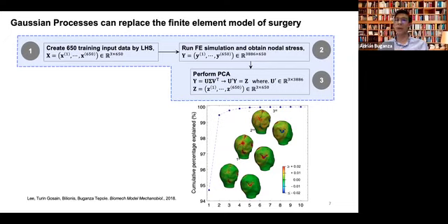So if you, for example, normalize the stress data, if you subtract the mean and divide by the variance, you can do a principal component analysis. And the eigenvalues essentially describe the variance that can be explained by these different eigenvectors. And then what we see is that actually for this case, only 3 eigenvectors describe 99% of the variance.